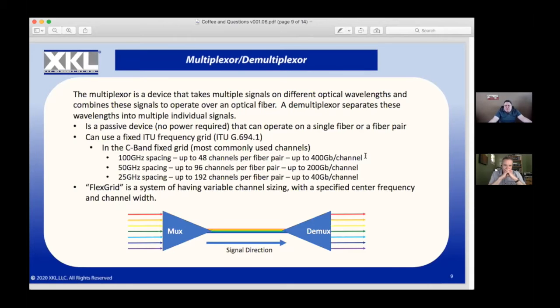Initially, it used to be 100 gigahertz of spacing, which in the standard bandwidth of the older fiber optic cables gave 73 channels assigned in the grid, but realistically, with the technologies we had, only about 48 to 50 channels were viable to work with the amplifiers and things.